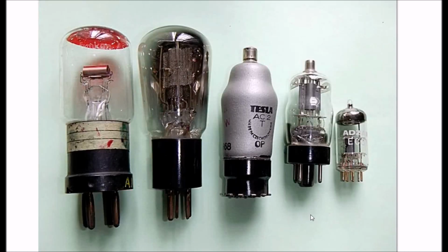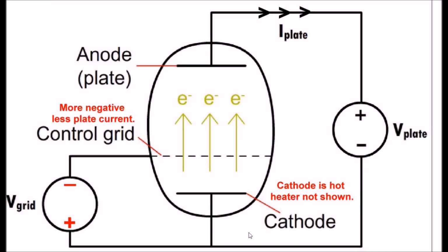These are vacuum tubes. This is the closest non-semiconductor device we have to a MOSFET. You could say these are the direct ancestors of your MOSFETs. What you usually have here with a vacuum tube is a glass or metal envelope that has all the air pumped out. You have a cathode, which is connected to the negative of the power source. The plate, which is the anode, is connected to the positive terminal of a battery. These things are high voltage.